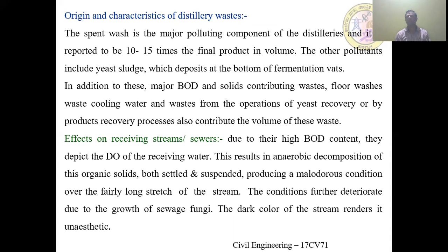What will happen if this waste is directly disposed on land or water bodies? As I mentioned earlier, the distillery industry has high BOD and COD values. When BOD is added to a stream or water body, the first step is that it depletes DO.